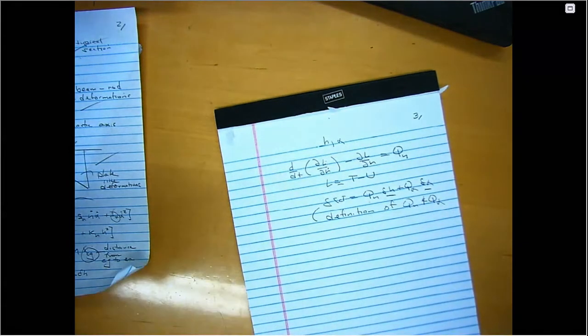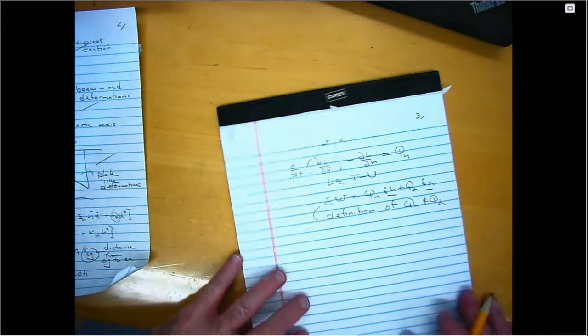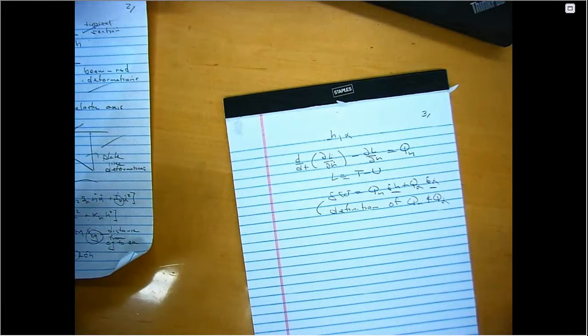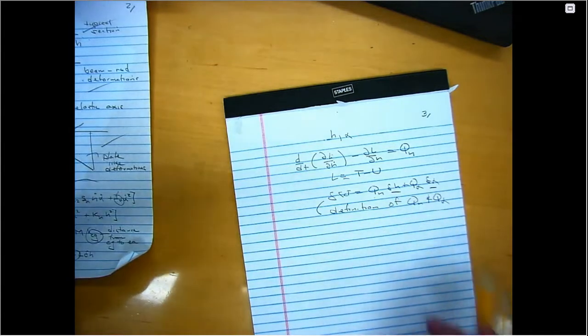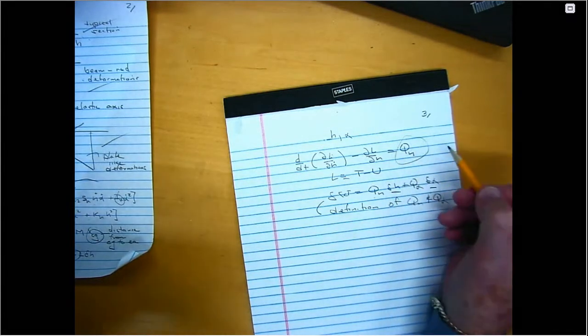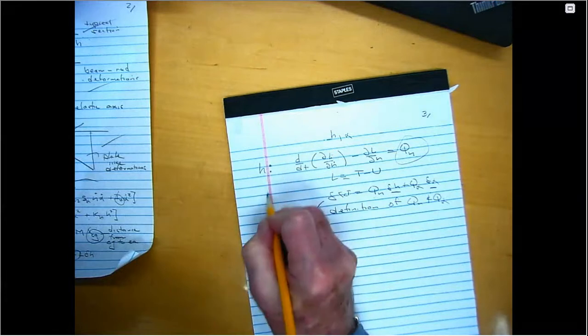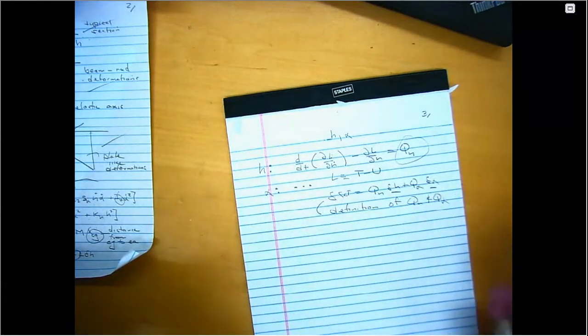So the way this works is unintended. Is that too sudden? No, I saw a smile or something. The way this works in virtual work is you have to be able to physically reason what the expression for the virtual work is, and then identify the coefficients of the virtual changes in generalized coordinates to give you the generalized forces, namely these things. So this is the equation for h, and then there's a similar one for alpha, which I won't bother to write now since it's the same thing, except h is replaced by alpha.